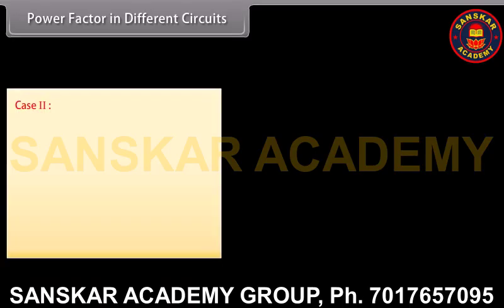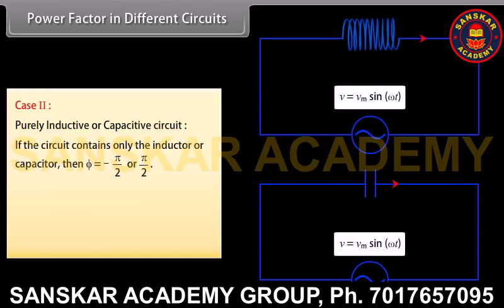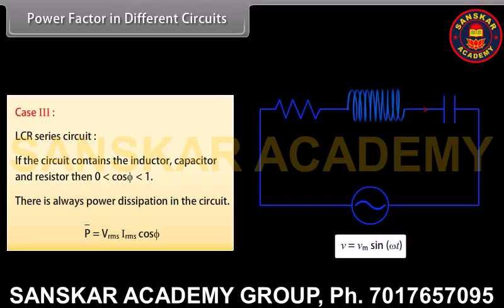Case 2. Purely inductive or capacitive circuit. If the circuit contains only the inductor or capacitor, then phi is equal to minus pi by 2 or pi by 2. Value of cos phi is equal to 0. There is no power dissipation. P bar is equal to 0. Case 3. LCR series circuit. If the circuit contains the inductor, capacitor and resistor, then cos phi lies between 0 and 1. There is always power dissipation in the circuit. P bar is equal to the product of Vrms, Irms and cos phi.